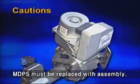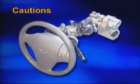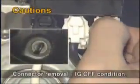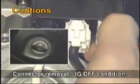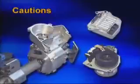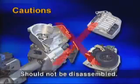Be sure that the MDPS for replacement is supplied in assembly state. Let's see the cautions at service work finally. At first, when steering wheel is assembled or disassembled, do not use hammer and the like. Secondly, the disassembling and connecting of the connector should be conducted in the ignition off condition. Finally, the MDPS system is supplied with the motor and column shaft as an assembly. Therefore, it should not be disassembled.